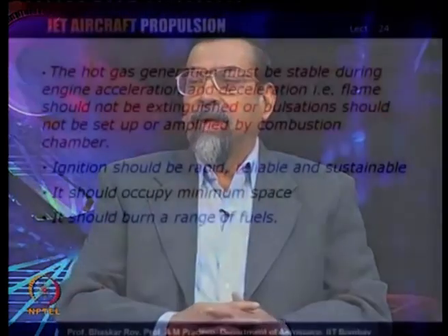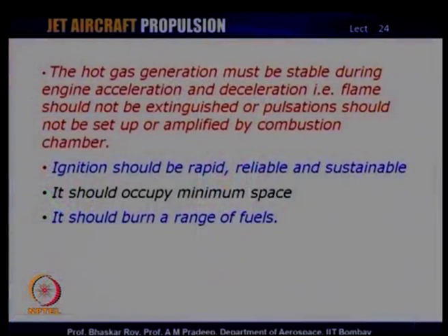The hot gas generation that must be created. Now, this must be done, as I mentioned, during engine acceleration and deceleration, and during acceleration and deceleration, the flame which is created inside the combustion chamber should never be allowed to be extinguished, or any kind of pulsations should not be set up or amplified by the combustion chamber.